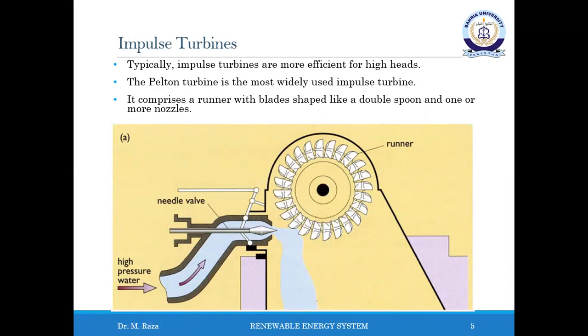The jet from the nozzle hits the runner blades and transforms the flow kinetic energy into rotational mechanical energy. Each nozzle has a movable needle to control its discharge. For a horizontal shaft turbine, the maximum number of nozzles is 2. For a vertical shaft, the maximum is 6. Each nozzle has a deflector, which is triggered when a load rejection occurs. It deflects the jet to control overpressure in the penstock and prevent runner overspeed.